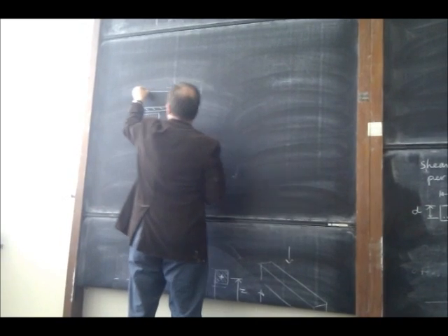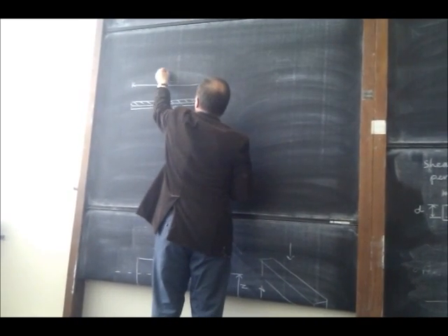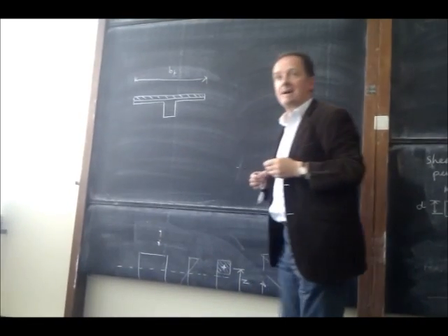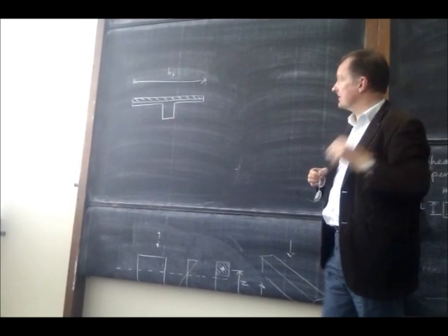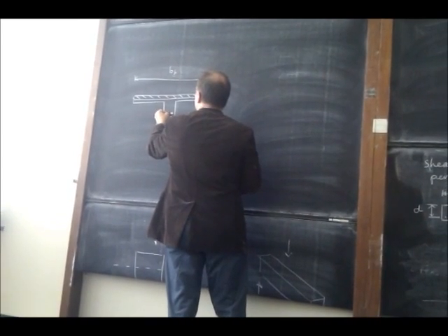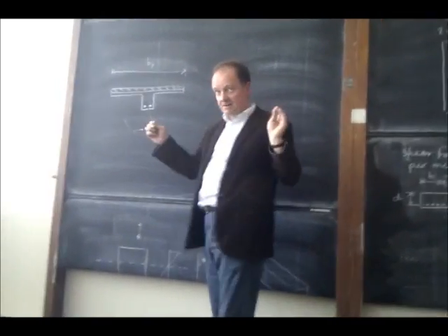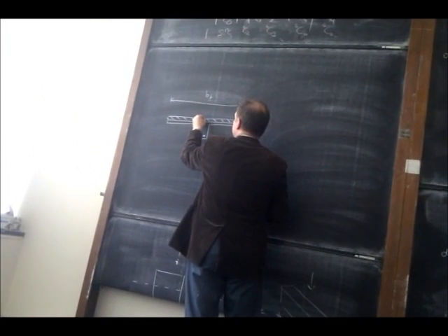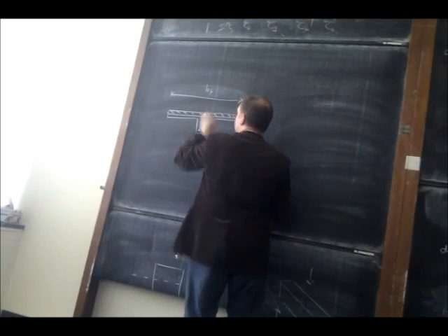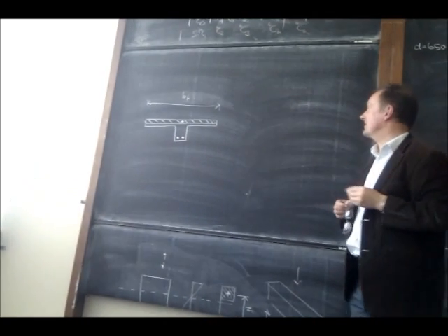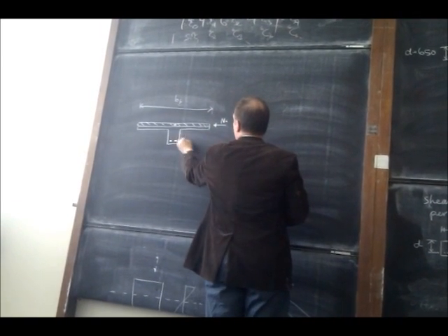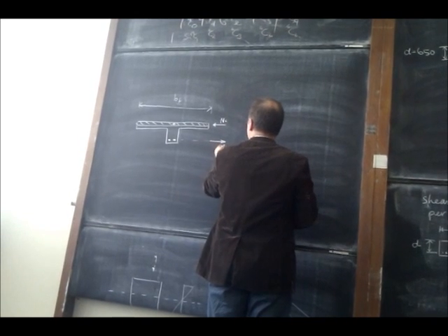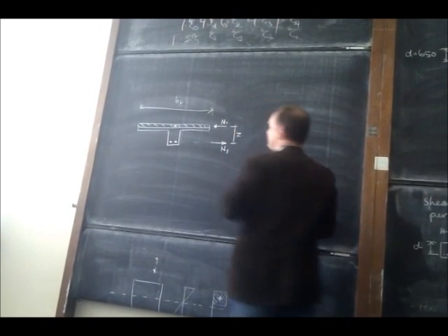So your reinforced concrete calculation would be based on that flange width. Now, in terms of whereabouts the resultant force acts, if that's uniformly stressed, constant depth, constant width rather, the line of action of the force is there, isn't it? In the concrete, it's in the middle of that stressed area. It's in the middle of the stress block. So the lever arm in this case, the distance between the concrete force and the steel force, is that.